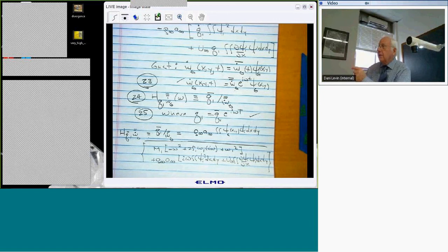And so if the input power spectrum is a real number, which it is, the gust, I multiply by a real number, the square of the transfer function, I get a real number out for the power spectrum of the output, and then I integrate that over frequency, which in this particular case, you could actually do analytically. Because after all, this is just a polynomial, a quadratic in omega, right? And even when I square it.